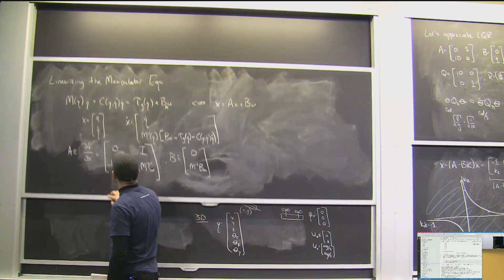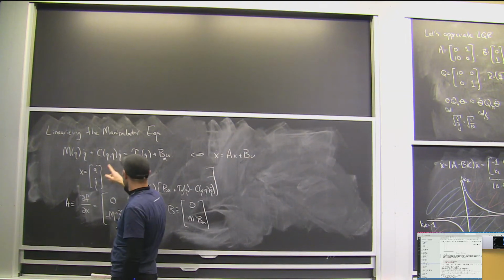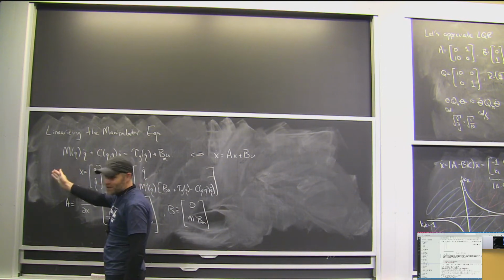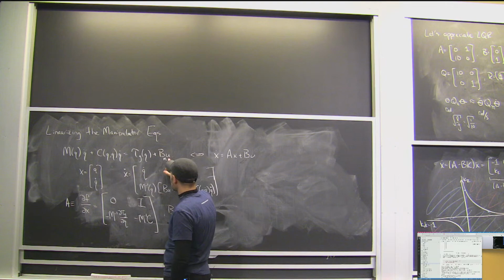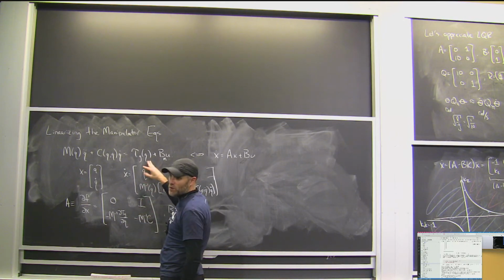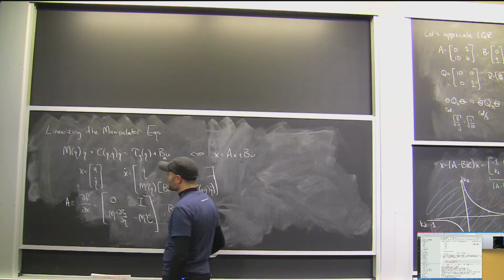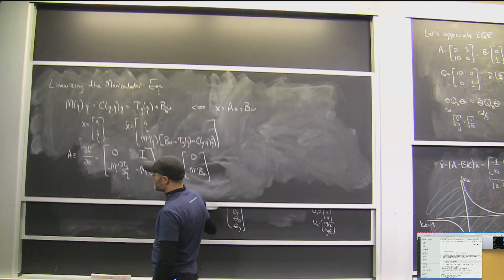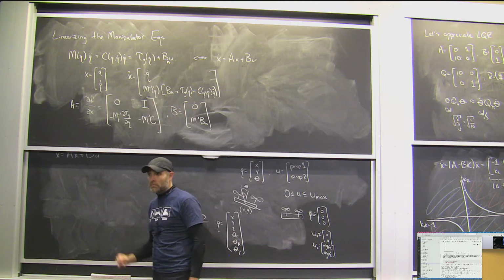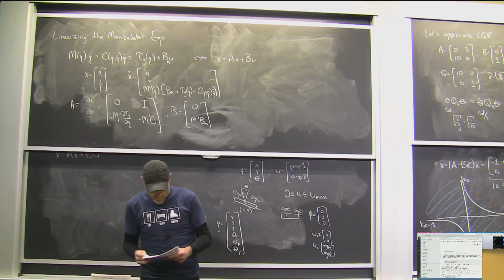For instance, for it to be an equilibrium point, Q dot has to be 0, so this term just drops away, right? Q double dot has to be 0, this term drops away. So really all you need to do is u equals negative tau_g, and the gradients of tau_g are all you need, basically. A lot of people make it harder than they need to because they think about it as x dot equals f of x, but for robots it's this. It's pretty simple. Great question. A lot of times that's a small nonlinear optimization to do.